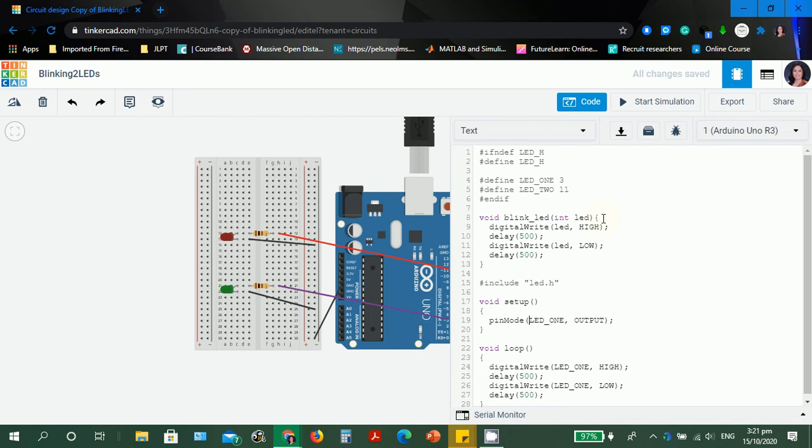So let's declare the status of LED 1. It's an output, of course, and another. Okay, you can actually copy. So Control C, shortcut, and then Control V. And then don't forget to change that this is for LED 2. You can do copy and paste, but always change the copied text related to the other, because you will have an error if you declared the status twice.